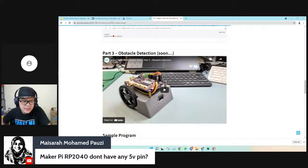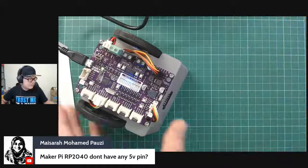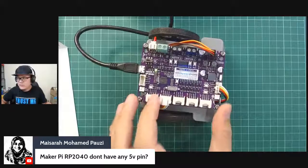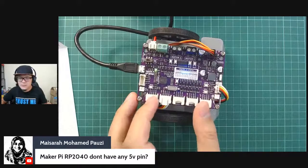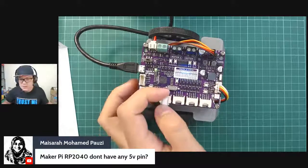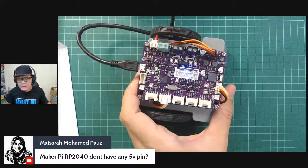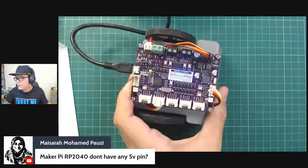Okay, the MakerPi RP2040 doesn't have any 5-volt pins. Yes, it doesn't have a 5-volt pin, so all the pins on the Grove connectors are 3.3 volts. So you need to use 3.3 volt sensors or modules to interface with the MakerPi RP2040.